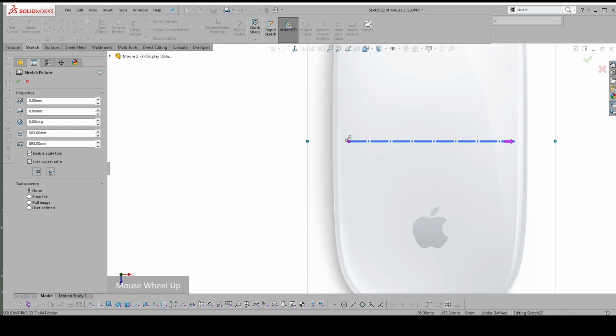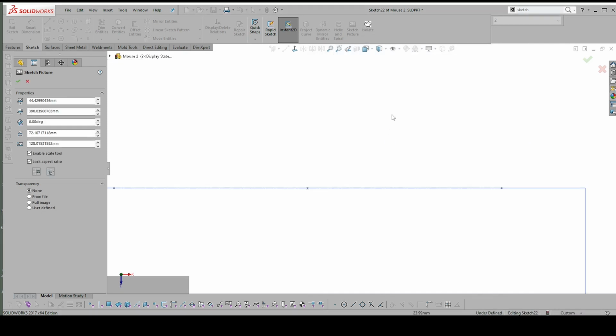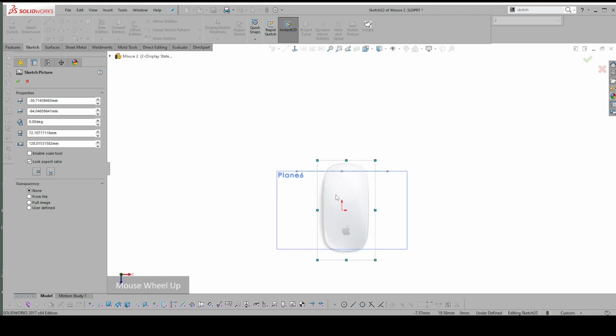origin. Right. So the way that the scaling bar works is you grab the left hand of the scaling bar, drag it across to the left edge of the sketch you want to scale it to, and then drag the right across to the right side, let go, and then you can type in whatever dimension you think that should be. So in this case 57, say OK, and that will have scaled the entire drawing. What I do here is I disable the scale tool. It just gets in the way, and it goes all over the place, so it's a bit annoying.